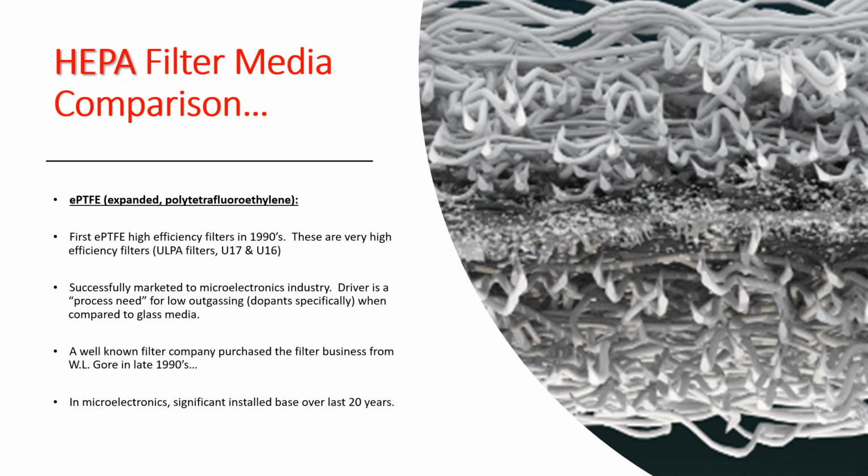So the first ePTFE filters were produced in the 1990s, so a little ways ago. I'm not going to tell you what I was doing in the 90s. Don't worry about it. And they were very high efficiency for microelectronics, so U16, U17 rating, which is the so-called ULPA filters. Beyond the scope of this discussion, but again, it was designed for incredibly high filtration efficiency. And it was very well received by the microelectronics industry because of the efficiency of the media. It actually allows for a lower pressure drop than glass. So as a result of that, it's very cost effective for operations that are running very high airflows.